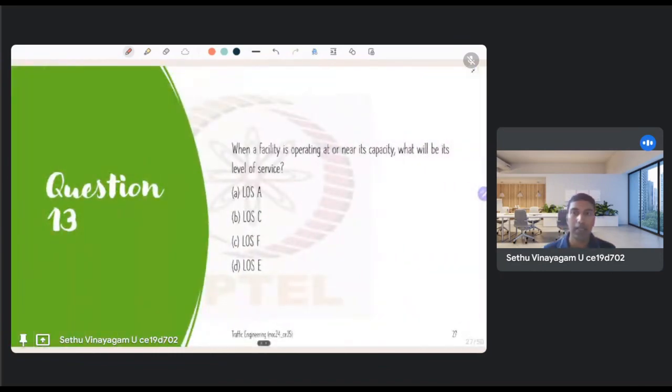Next, question number 13 is, when a facility is operating at or near its capacity, what will be its level of service? So options are LOS A, LOS C, LOS F, and LOS E. Okay, so here, LOS A is the best LOS that you can get, and you have up to LOS F, which is corresponding to the worst condition, right? So LOS A, this is like free flow conditions. LOS F is the breakdown condition where your demand exceeds the capacity.